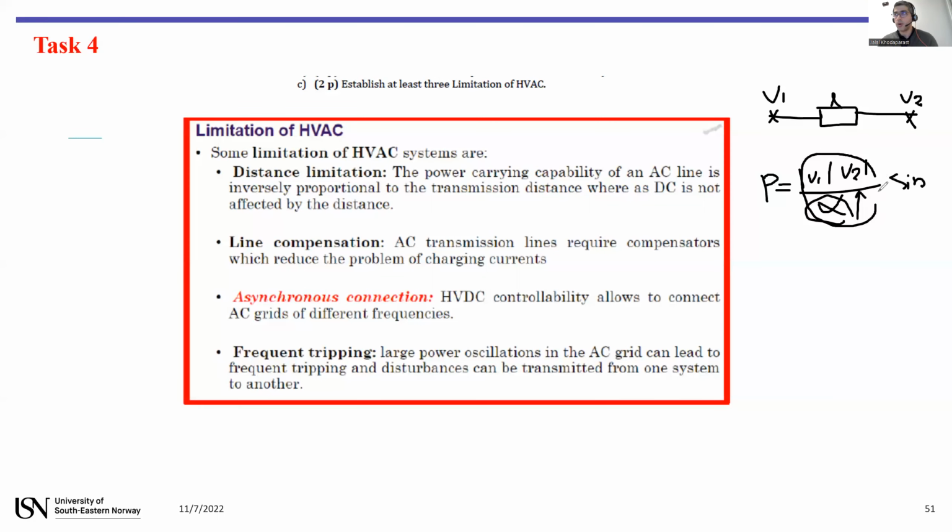So this is the maximum active power that the transmission line can send to the other side. According to this curve of P versus delta, if you increase the reactance, this peak will decrease. So with a long transmission line, the whole power you can send from one side to another will decrease. It's one limitation.